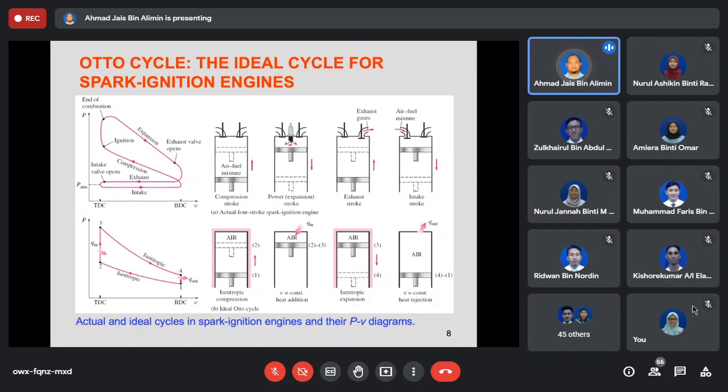Okay, compression stroke, you go up to the top dead center, and then you have the ignition, going downwards. Once the piston reaches the BDC, it goes up again. During the journey moving up, the piston pushes out the byproduct of combustion through the exhaust port.